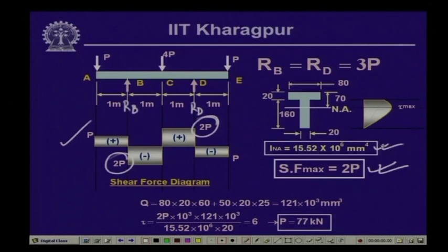Now, as we have seen, in the case of rectangular sections we get maximum shear stress at the neutral axis. For this component, at this particular section our shearing stress is not 0, but has some value which we call tau minimum, because you have some area for which you get the Q value, which is A y bar. When we took the rectangular section, above the top surface we did not have anything, and that was the value of 0 shear stress.